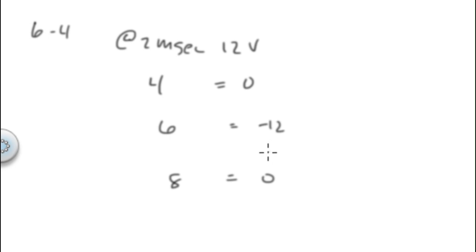All right, so number 5. For the waveform of 627D, find the voltage at t equals 1 second, 2 seconds, 9 seconds, and 9.5 seconds. So at 1 second, it is 3 volts per second, so it's at 3 volts.